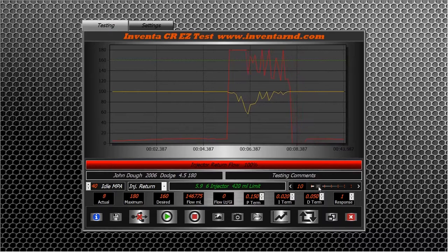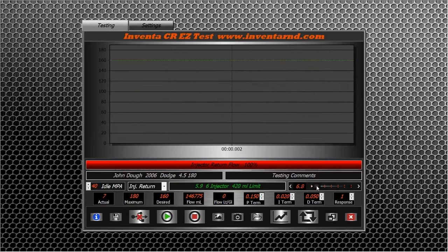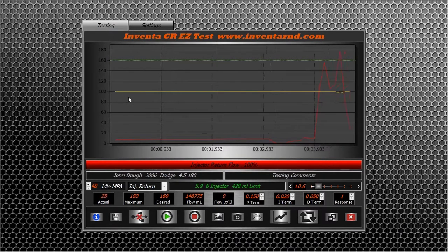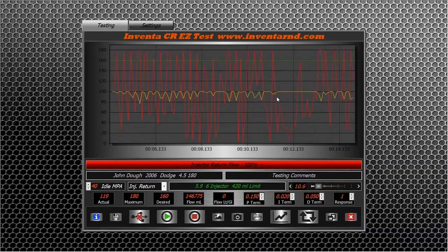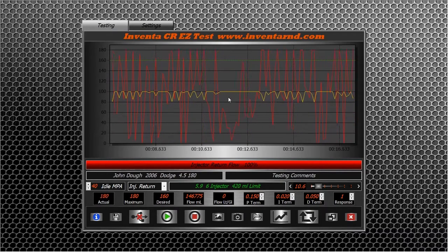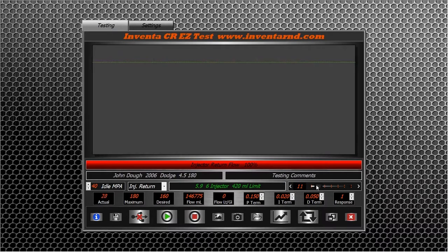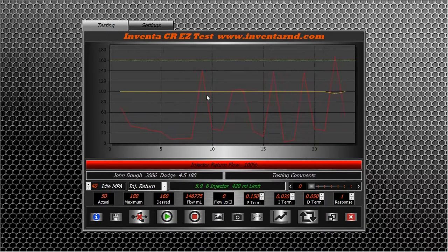But if you want to really have a time tag and a pressure tag of what's going on, we'll start the scope back. If you put this to 0, it's going to be a free run. So what's going to happen if we're set to 10 roughly, you'll see things start accumulating on the screen, and then once it gets to 10 here, whatever it's set at, then it's going to start scrolling across the screen, and new data is going to be added as old data goes away. So if we set this thing to 10, it's going to continuously plot data until you stop it. So if you want to say, I want to run a test for 2 minutes and see what happens.